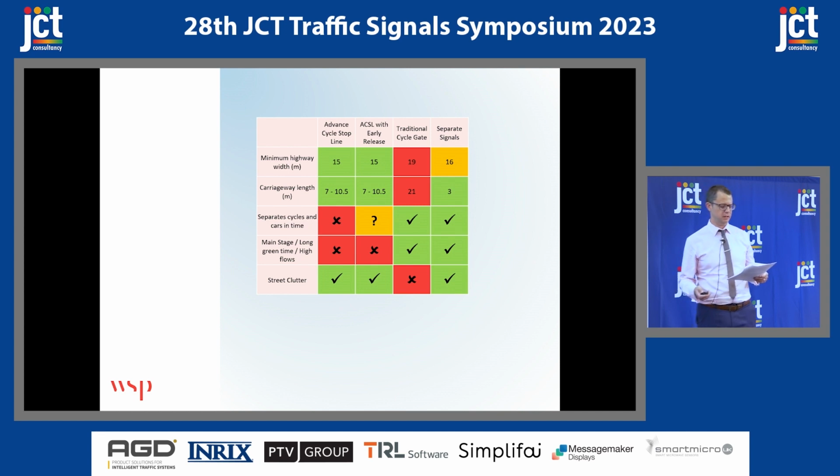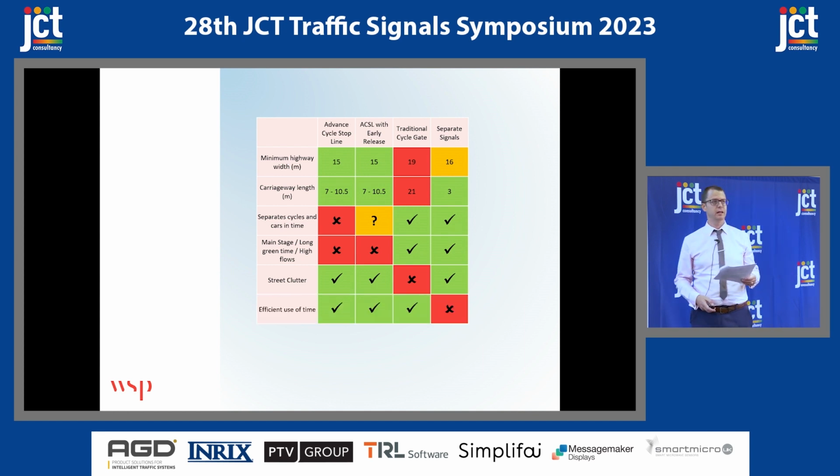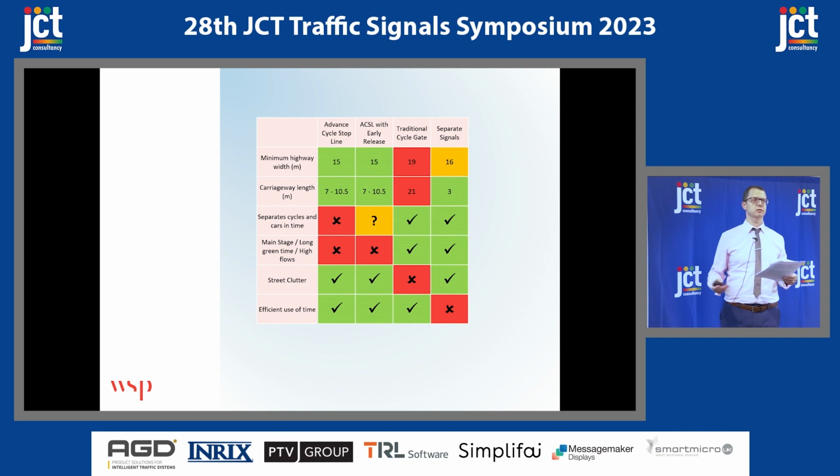It fully separates cyclists and other traffic, and it doesn't add much street clutter. It's looking good. However, it might bring an extra set of intergreens into play, making the signal times less efficient and cause additional delay for all junction users.